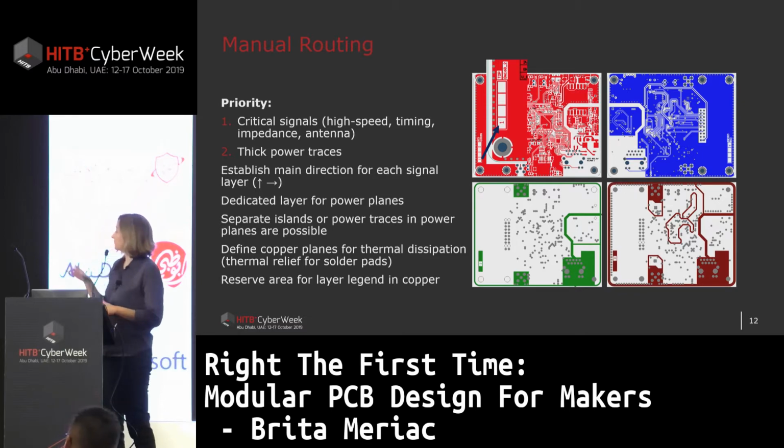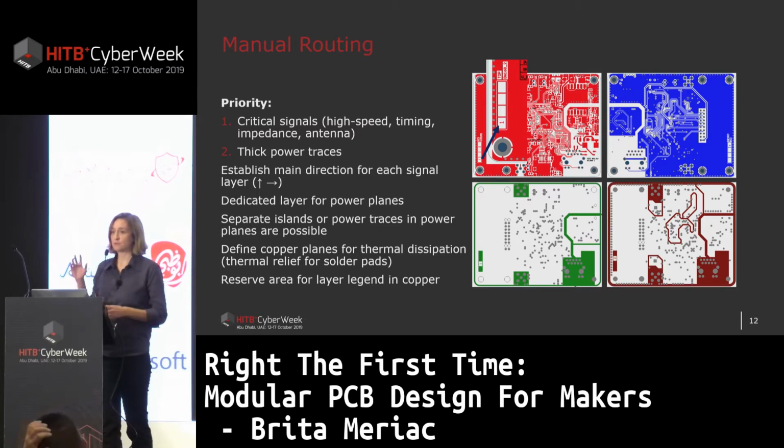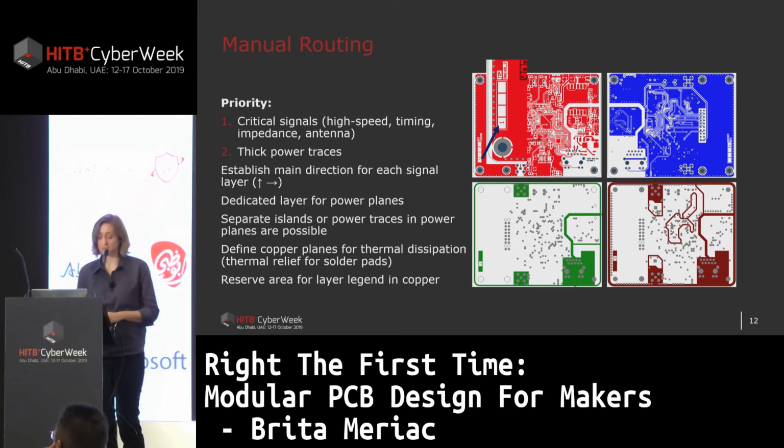Otherwise, here on the 4-layer ones, the inner planes are not just for one power source. You can divide those planes into different power levels, or even build islands or thick traces that connect different power levels. Also, you can just write text in copper. It doesn't have to have a net name, or it doesn't have to be connected with a net. So the PCB production will surely appreciate to have numbers for each layer on the copper, and also your project name or project number.